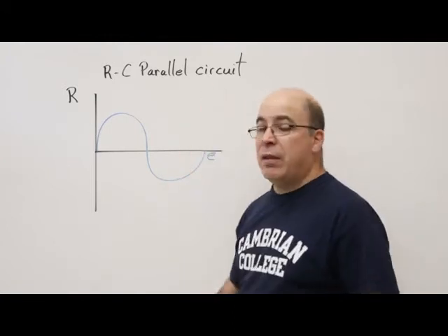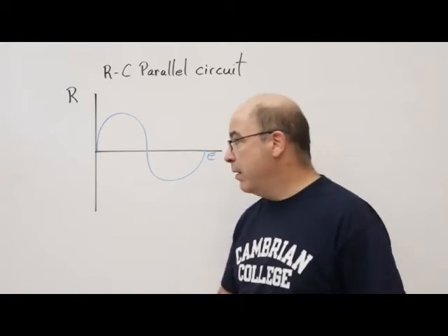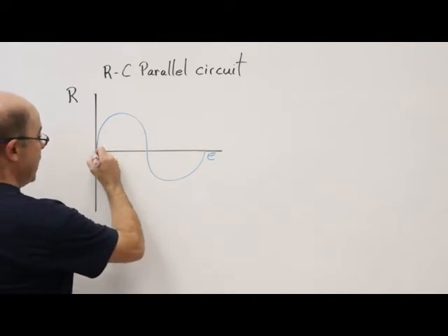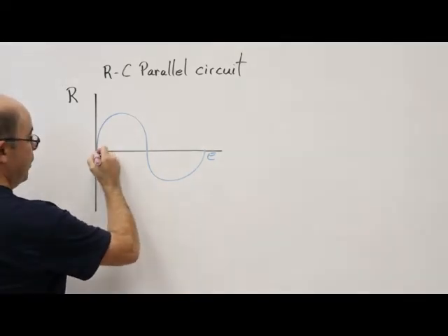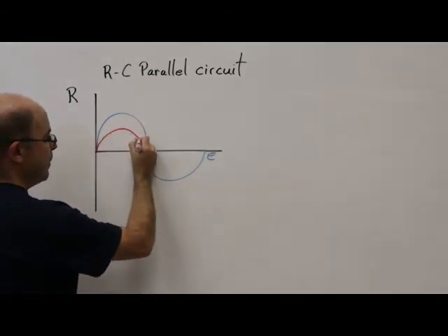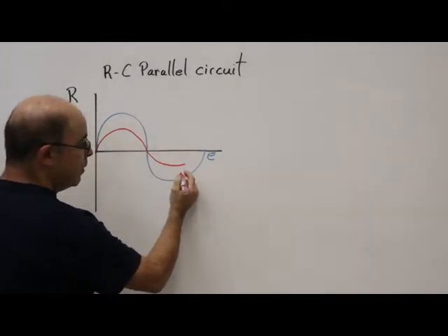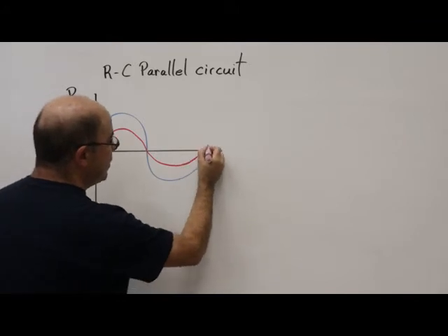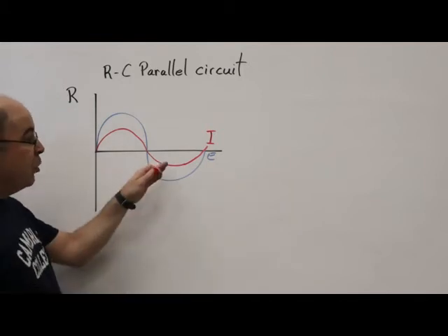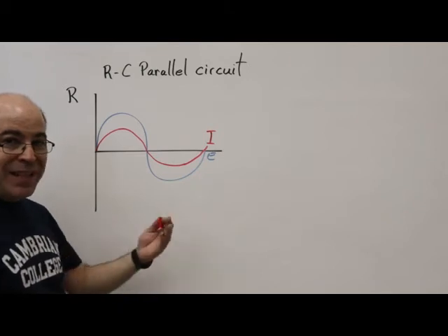So it doesn't really matter if it's a parallel circuit or a series circuit, because we're going to draw it the exact same way. With the voltage waveform, my current is going to be basically starting at the same point. It will rise in unison. It will collapse in unison. It will cross over at the same point and will follow into the negative alternation and continue the same trend. We're going to identify it if you're using the same color of marker, and not like me where I've got two different colors that we can see.